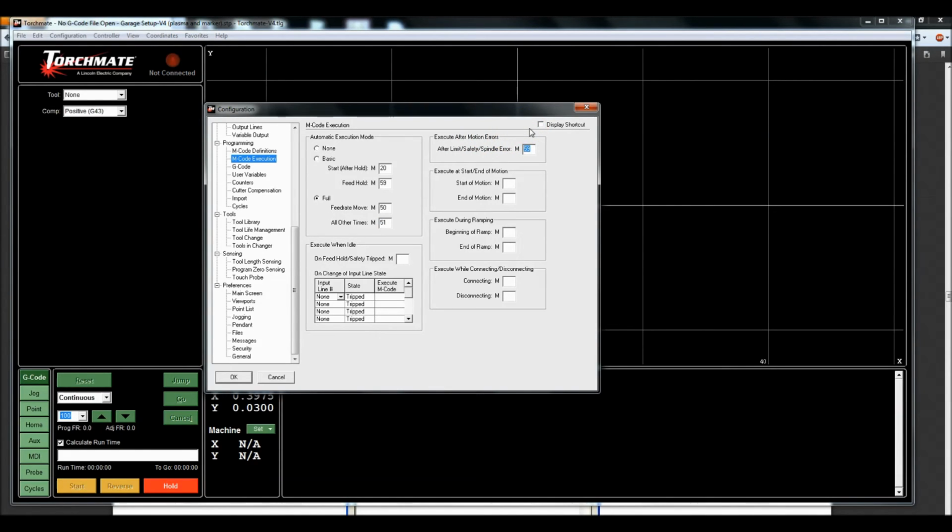And I like doing this because I have had situations where a tool will fire and keep firing until I go to the aux section and turn it off. And I don't want that. I want it to just shut off automatically. So I have an all off. I put the M59 code here. I would recommend doing it.